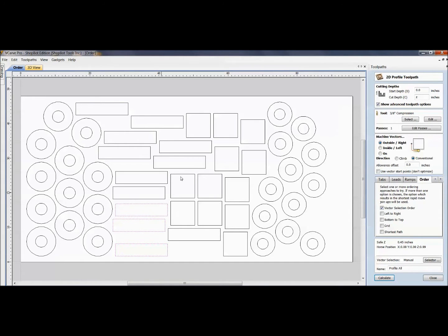selected these in. So, something like this where you're jumping around, selecting here and then over there, that's not going to be very efficient because you're going to have your machine cut these three, have to pick up, travel above, go down over here, pick all the way up, travel here. You got a lot of back and forth going on. So there might be times where you need to do that with specific cuts, but just so you know that you can order your cuts right here.